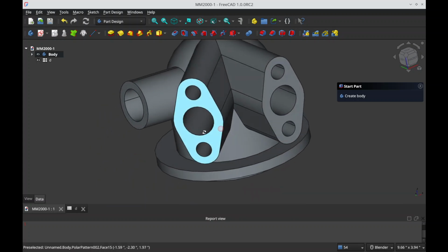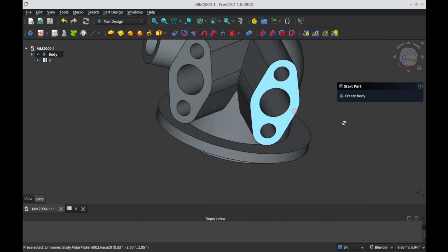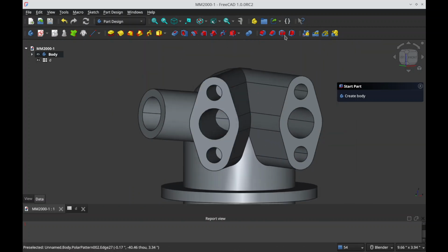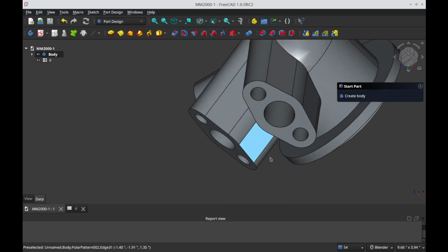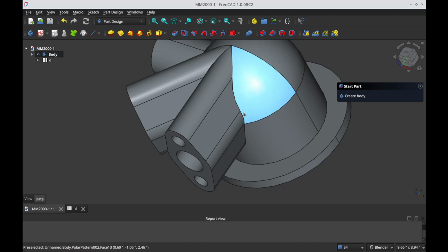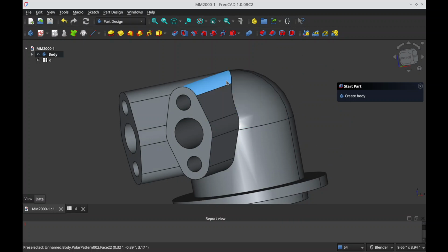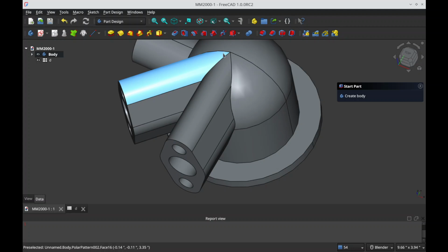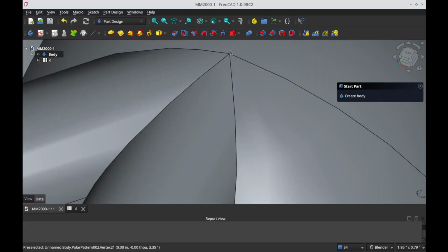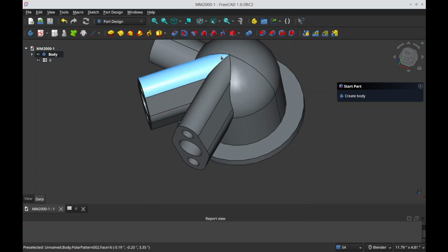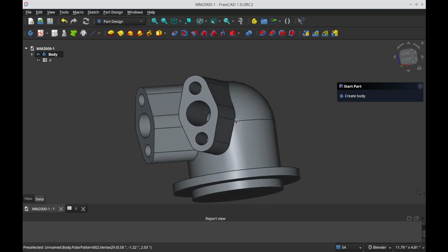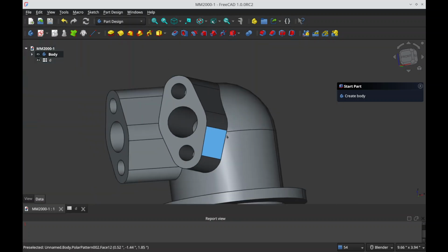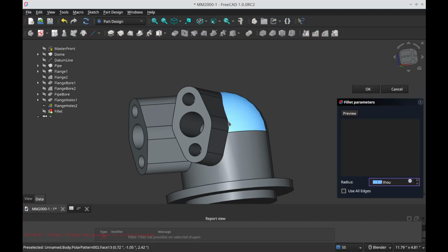We just need to do the fillets, and the fillets are a real pain. Let's just see what we could try to view it and infer what's going to happen, but where we're going to struggle from the last time I was doing this is along this edge here. You just have 1, 2, 3 faces, and then additional 1, 2 faces at this central point at the top where, yeah, 1, 2, 3, 4 faces all meet at the same time. You might also get issues from here to here, and let's try it. Let's just try it.